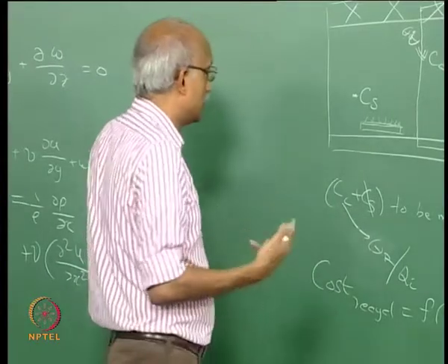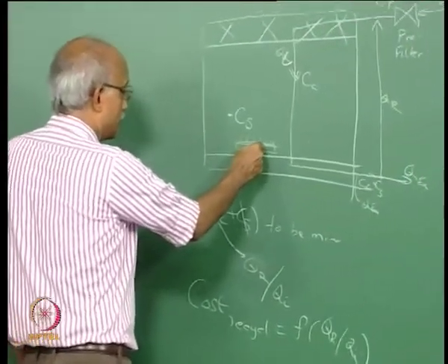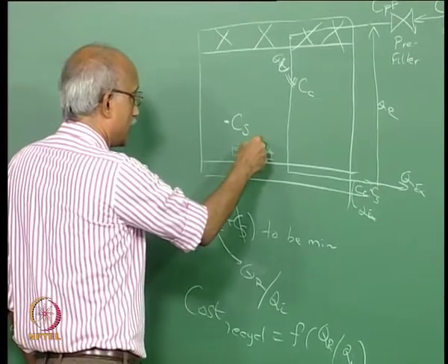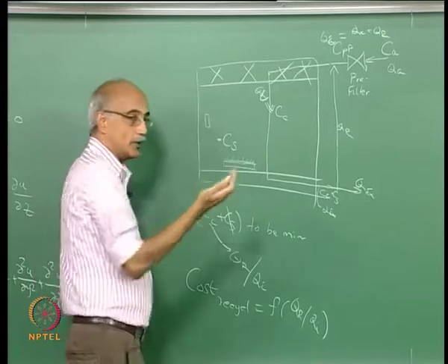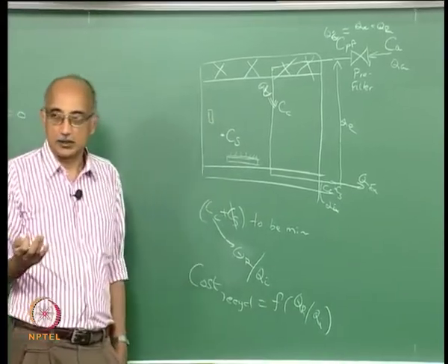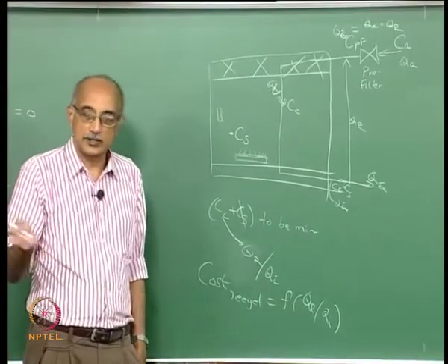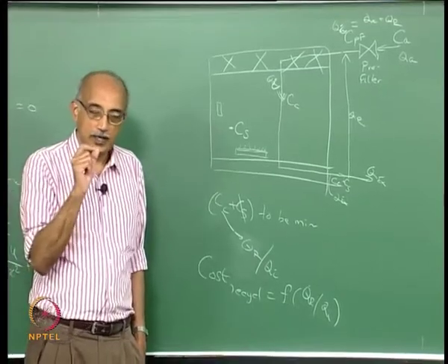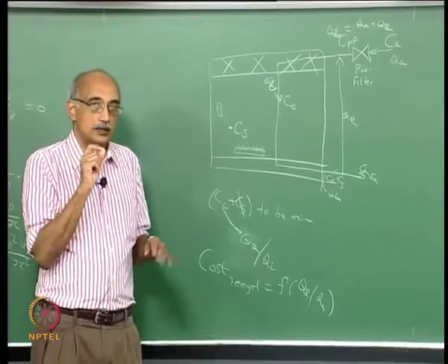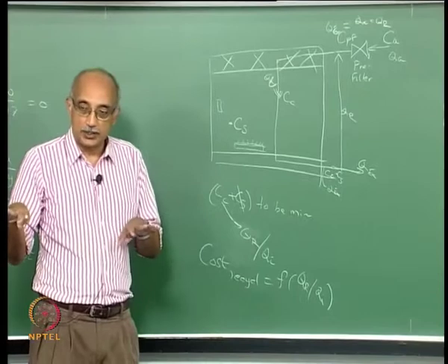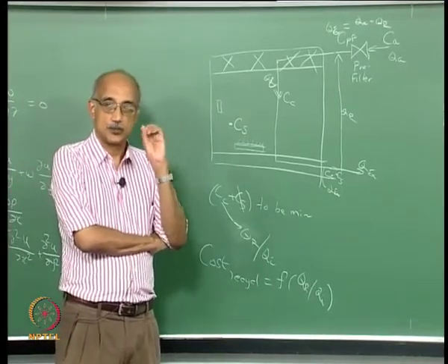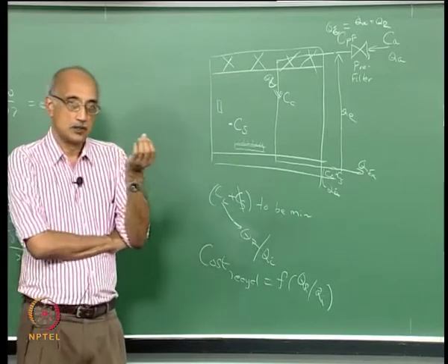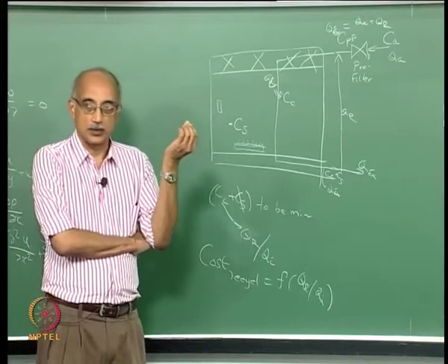Placement, because if you place your wafer here, the rate of deposition may be very high, but maybe if you place it over here, it's very low. So, you have to do some mapping of airflows and particle levels in the clean room, identify regions that are relatively clean compared to regions that are dirty, and make sure that you perform your most critical processes and expose your most critical components only in the cleanest locations.